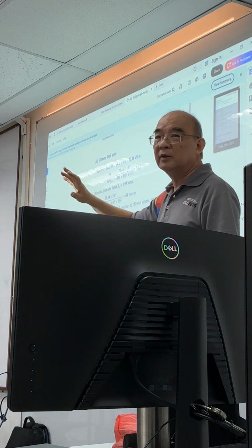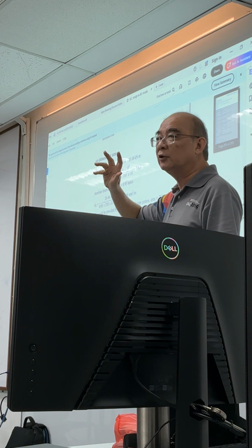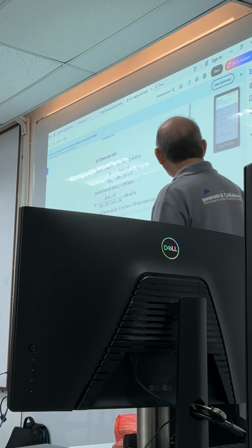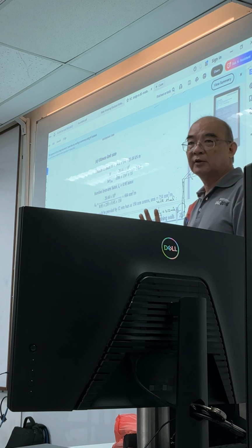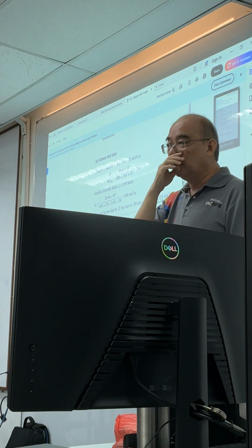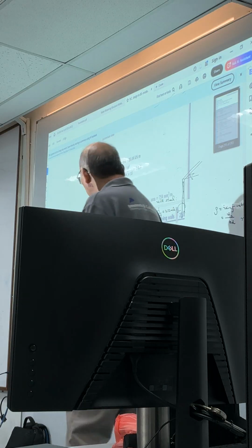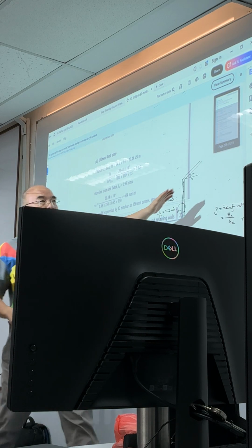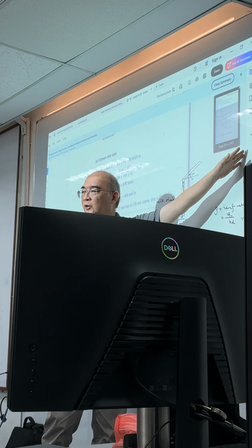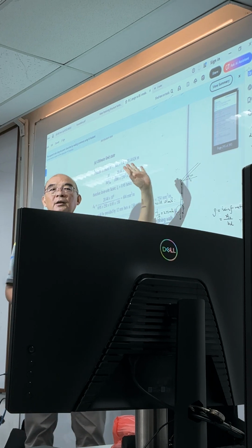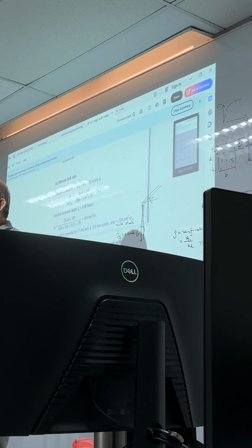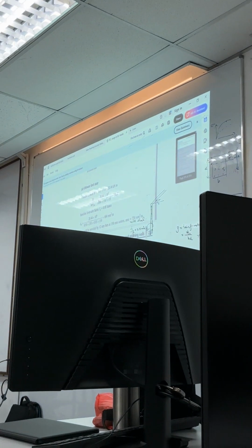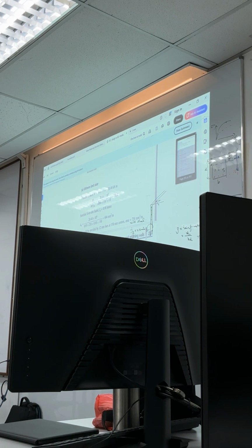If you don't over-provide so much, the rebar stress will not pass the test. So the next thing is you go and calculate the rebar stress, and you find that even if you over-provide 25%, the rebar stress is still more than the stress allowed.